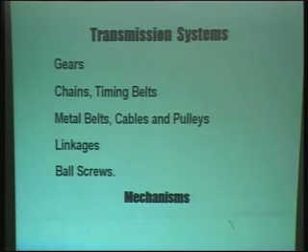Then once you have got the actuator, you have to convey the motion to the point where you require the motion. That's what you have to do. So you use gears. These are well known. I don't have to go over them because you all know about gears, gearboxes. Lighter the gear, the better, because the gearbox has its own inertia when you want to accelerate. You need mostly a positive drive, but of course, so that's quite important.